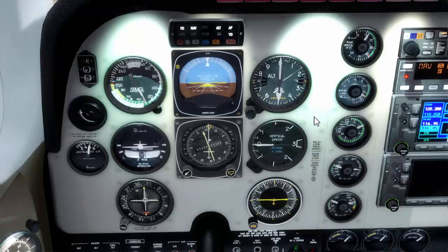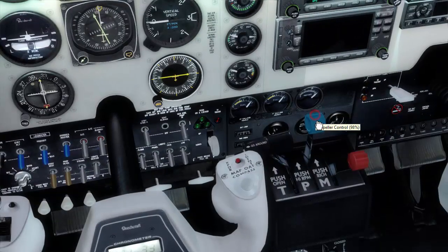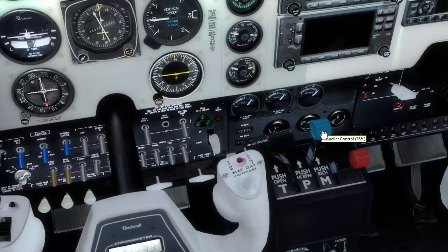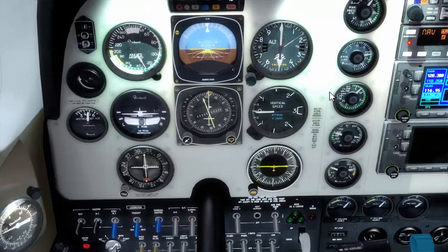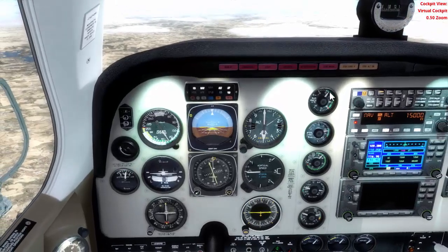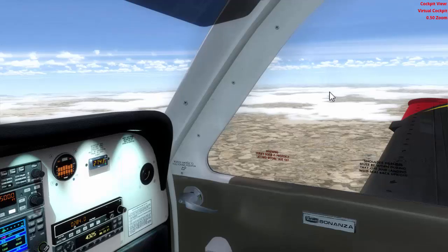So when we are flying, we need to monitor our gauges. And what I told you before about the manifold pressure gauge, that as soon as we ascend, we get a lower value, because the air density is lower. Anyway, I will reduce the propeller control, the RPM, a bit, and I will put this to 75% more or less, because I want the engine to be more rested when working. And we are doing a comfortable flight.